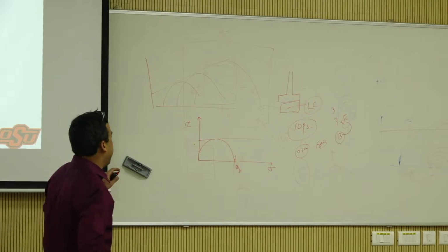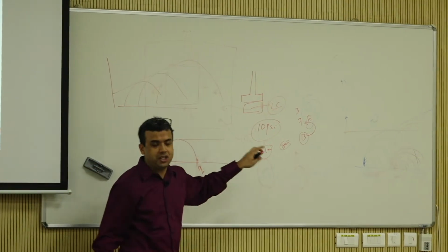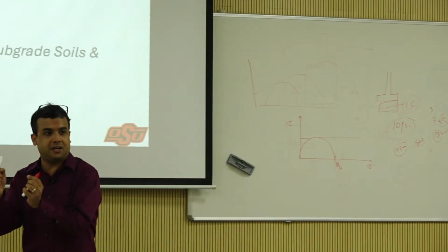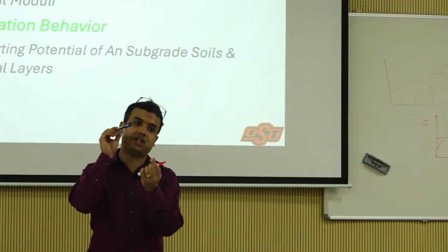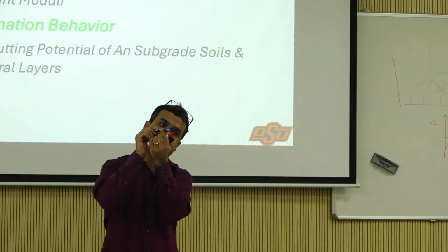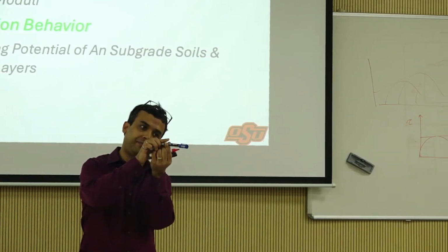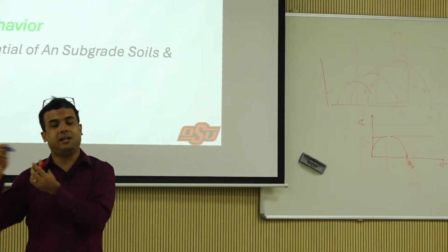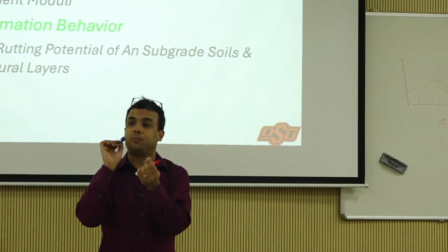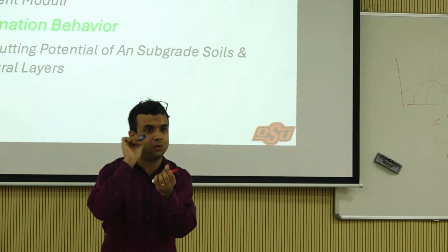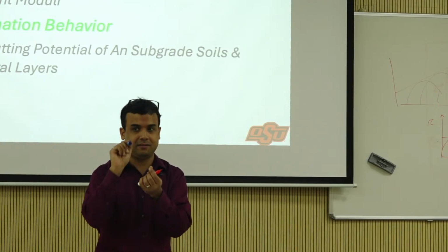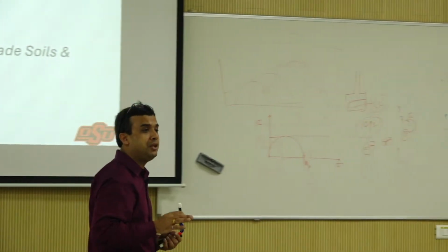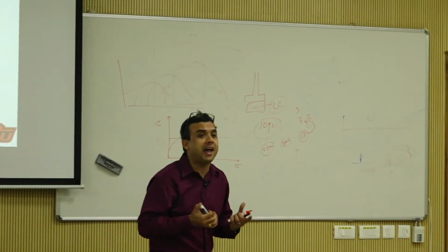In triaxial testing, or shear strength testing, it's called monotonic triaxial testing, because monotonic means you are just pushing it at one given rate. Other than that, resilient modulus and stuff, when we get into that, it's going to be called repeated triaxial testing, because you're going to pulse it. That makes sense? There is another term a lot of times people use. They call it dynamic triaxial testing.